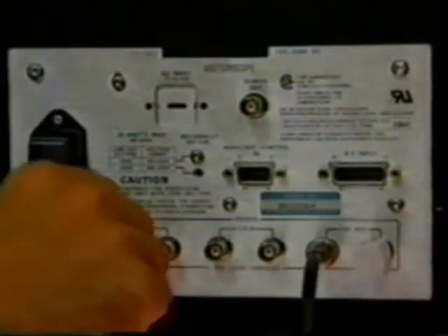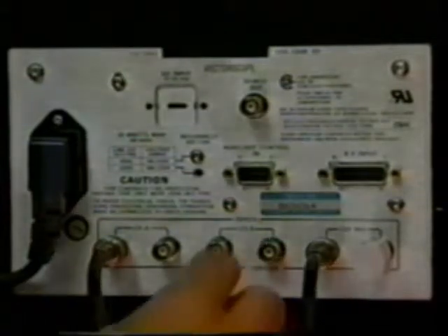Now let's check the white balance. First, be sure to connect the video camera signal to the Vectorscope input. Next, point the camera at a white reference. Use the variable gain knob to expand the trace. Remember, the center of the display is black and white, so we not only get color information, but can also see if there's no color information, which is useful during white balancing. Then press the camera's auto white balance. Here's how the signal will appear if the camera is working properly and the white balance is correct.